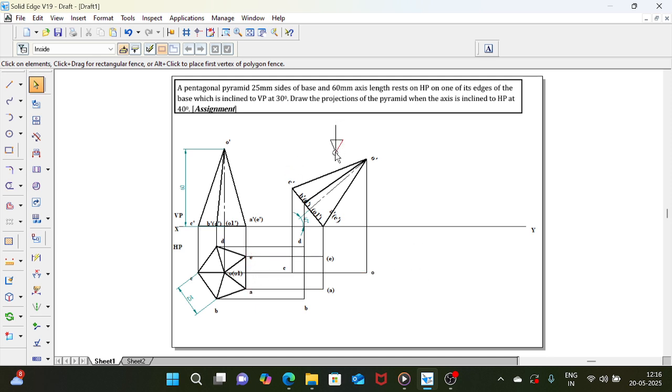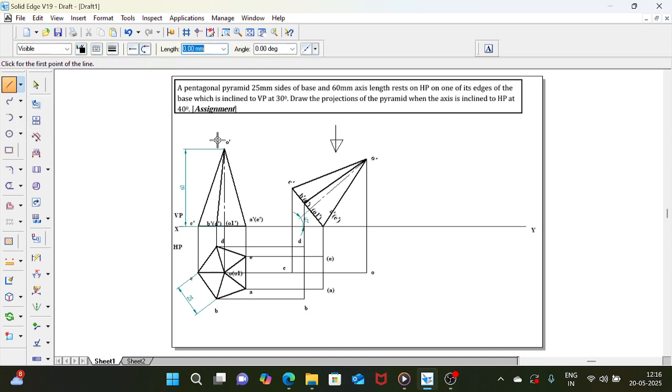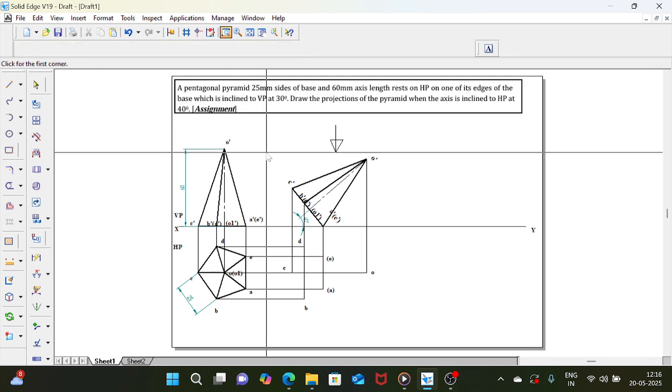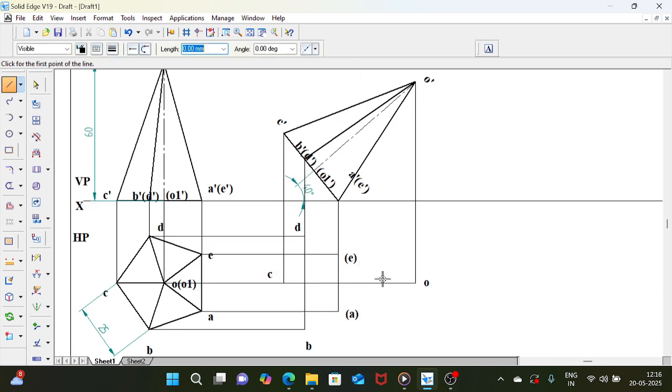So now when you see from the top, the base is not visible, the apex is visible. So first I will fix the boundary. What are the boundary lines I will fix? Here you see, I will zoom this and mark. See, O is the apex. From O to A, is it a boundary? I don't know. If I try to join A, O to B, here you see A is coming inside. So this A point is inside this OB boundary. So OA cannot be a boundary.